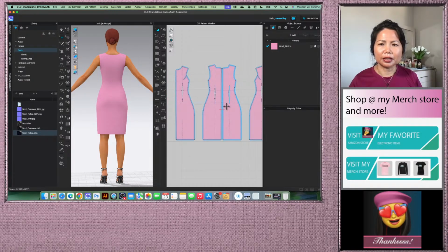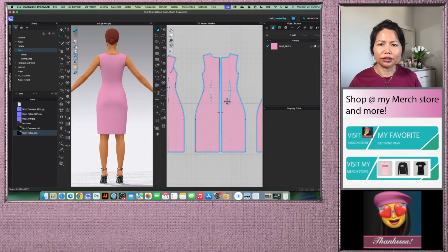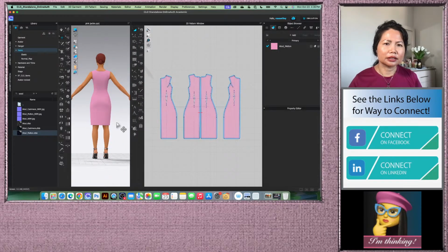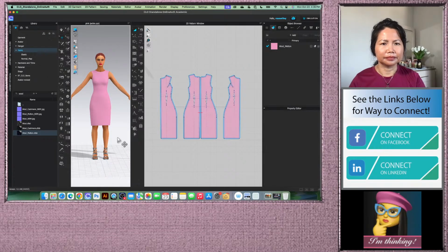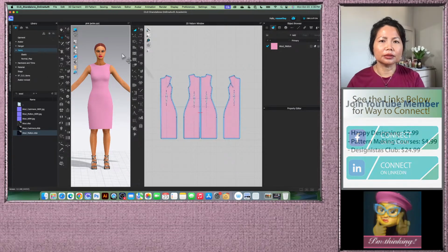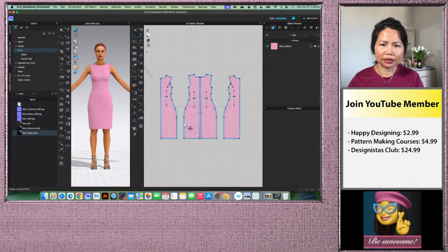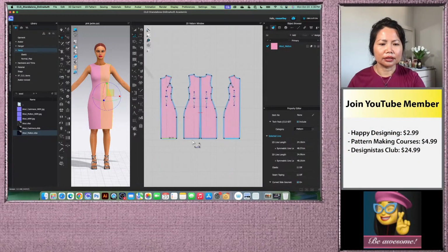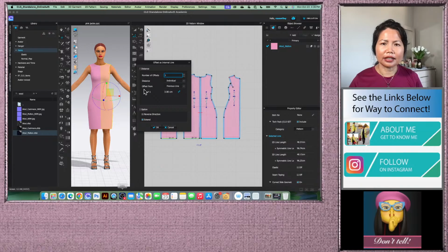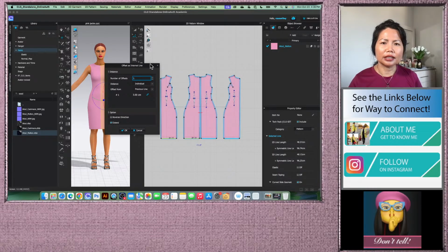And let's simply cut until making the trim. So here I'm going to use this edit pattern tool, click right there, press shift, click right here, right click, and we want to select offset internal line here, and let's create that too.